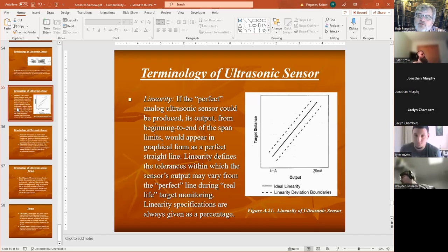The sound wave is converted, that distance, say if it's set up to run between 4 feet and 30 feet, it'll convert that distance. Anything between 4 feet and 30 feet gets converted to an output signal. In some cases, it'll be a voltage output. The example they give you here is a milliamps output, 4 to 20 milliamps.